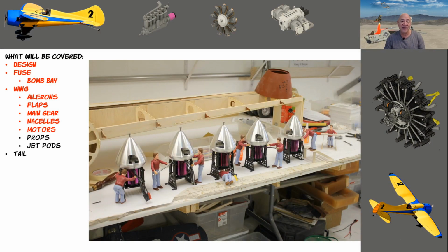It was Hacker A60-16Ls, which would turn a 21x14 three-bladed prop. That's the pitch speed I needed. Now, keep in mind, I think this plane would have flown vertically if all 6 motors were put on 10S. I was going to fly this airplane on an 8S, which was going to give me about 2,500 watts per motor. Take that times 6, and that's a lot of watts. And the watts per pound on this airplane is going to be like 150 watts a pound. So it would have flown like a pattern plane probably, but it was the Hacker motors.